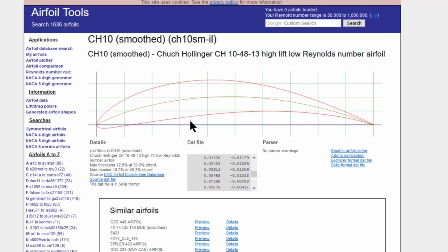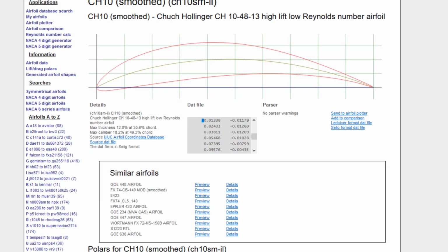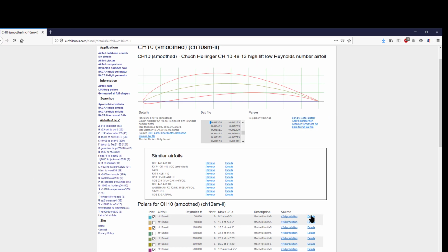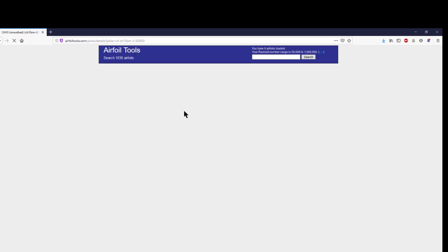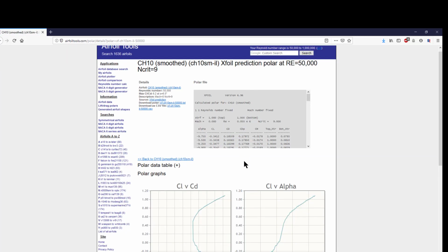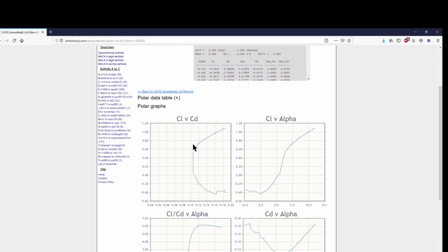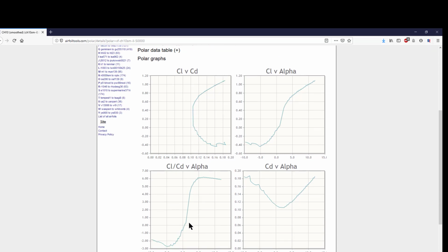But all that this shows you is an outline of the wing, which I've also included on the resource page, and the plots. Now, interestingly enough, I can come down here to my Details tab, and we'll do this later on, and I can select my wing details, and now I can see this coefficient of lift versus coefficient of drag plot, and you'll see where this happens, coefficient of lift versus coefficient of drag versus AOA, and you'll see that's that peak point at 5 that I was pointing out.